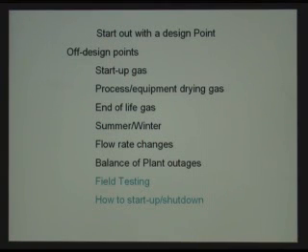The other two considerations are going to be field testing. Sometimes we have to test the machines in the field, and that means we either test them on the process gas once the rest of the plant is operational. But of course, once the rest of the plant is operational, the operations guys want it so that they can go ahead and make some money, and so they're not likely to give you a week to do that field testing. So you end up field testing on whatever gas may be around, and usually there's lots of air. And so depending on the field test requirements, we may have to identify how long and at what pressures and flow rates we can operate on air so that we can verify the machine is mechanically sound once it's at the field.